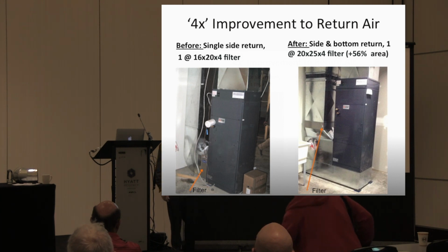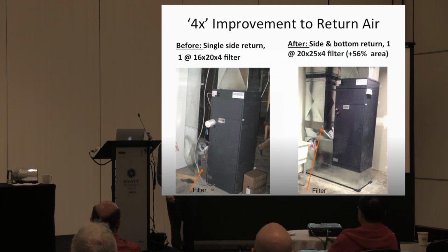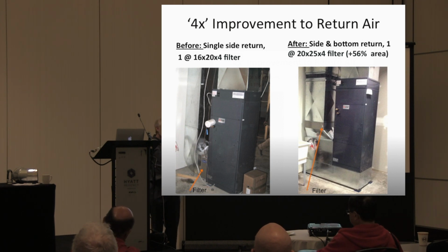I walked in there because I had a commercial interest in the ventilation system, and I said, Mr. Contractor, please humor me. Take a few statics for me. I want one in this cabinet, one right here, just to find out if this duct system's going to work. Anyway, he says, screw off. I'm not going to listen to you. Basically, this is the way the sub always does it. This is after recommending to this builder 2 good quality red seal sheet metal workers who could do a proper job of a heat pump, which is air sensitive equipment. So he went to the plumber, because that's his regular trade, who's completely incompetent.